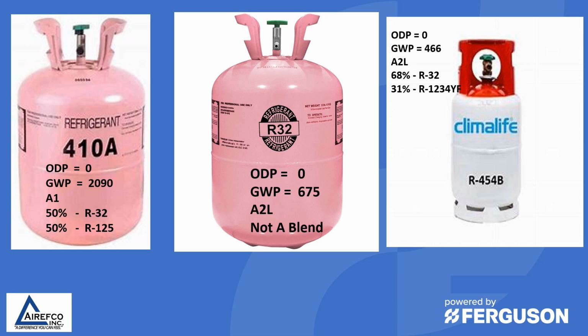It has an ozone depletion potential of 0, a global warming potential of 675, and is an A2L refrigerant, but because of the global warming potential, Carrier has decided to go to 454B, which has a 0 ozone depletion potential, a lower global warming potential of 466, well under the 700 standard according to the federal government. It is an A2L refrigerant. It is a 68% R32 and 31% R1234YF refrigerant mixture.